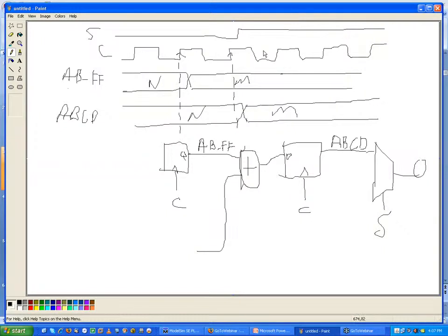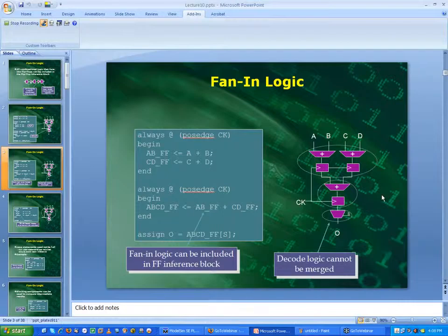So this actual O here, it's going to be delayed some time from whatever S and the delay we might have here coming out of the flip-flop and whatever this selection logic is. So maybe O is somewhere over here. It changes. It might be out here somewhere. Okay.